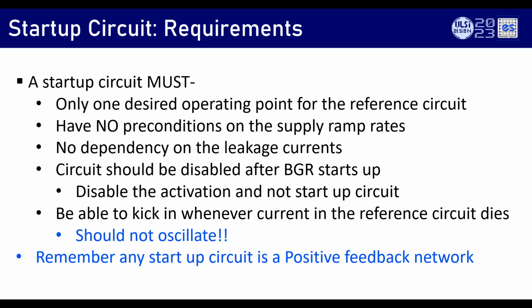And it should be able to come back again if the bandgap goes into the 0-0 condition. It can also go at any point of time. Then the startup circuit should kick in, and again it should put it in the correct operating region. And it should not oscillate. And please remember that any startup circuit, however you do it, is a positive feedback network. Okay. Any startup, however you do, is a positive feedback. So if you're going to give a strong kick on the startup network, it's going to oscillate.